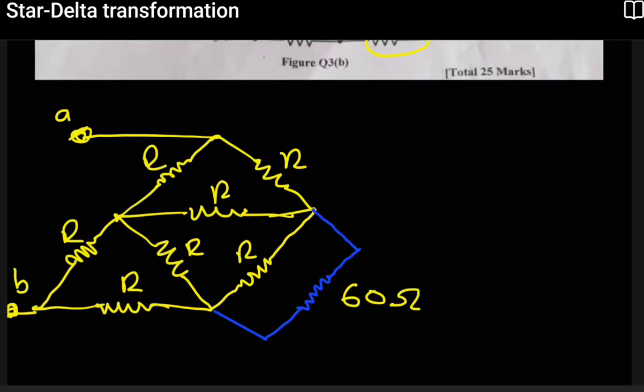The next thing that I want you to observe here is that before we even bring our star here, observe that these two resistors, these ones down here, these two are in parallel. The key thing for parallel here is that when you start from one point, you should only have two junctions. If two resistors are parallel, they should only have two junctions. There shouldn't be anything else.